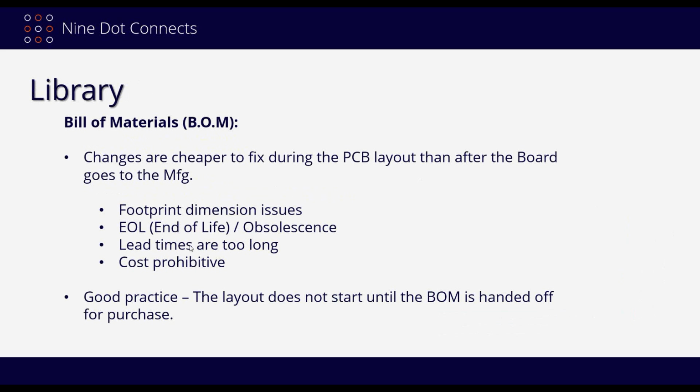But bill of materials, I can't emphasize enough that when you are done with your schematic, before you start layout, do your bill of materials. Deal with it right then and there. Because most people will say, no, I've got to move on to the layout because I've got management watching me. Okay, now I've got this thing pushed over to fabrication, and now I'm going to go back and look at my bill of materials. Well, there are several issues that you're probably going to come across here, which almost guarantee a respin. You may have footprint dimension issues.